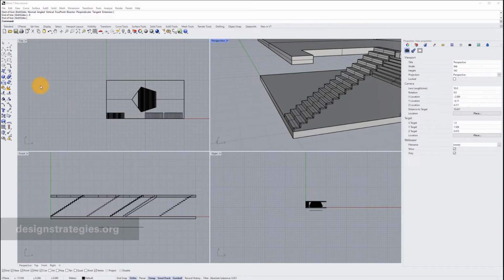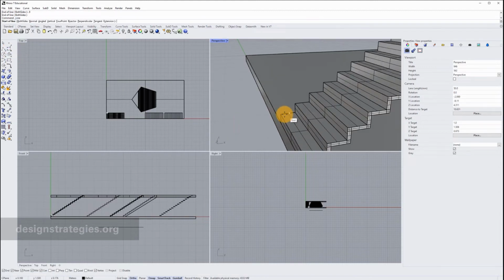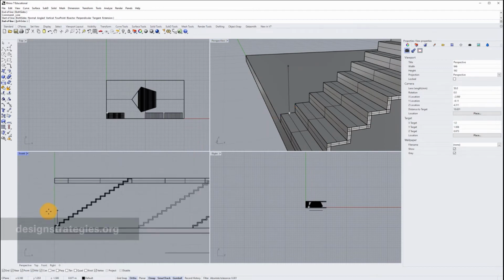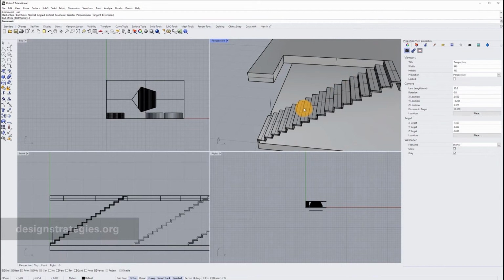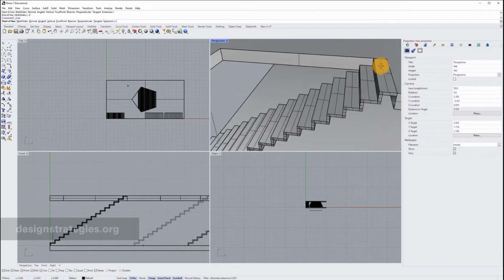The next way we want to look at how to draw a simple banister, I just take my single line and I just choose the midpoint of my staircase step here like this. And then I go into my front view and I enter a height of 90 centimeters, something like this. And I finish with my right mouse click. I do the same thing on the top. Something like this. I go here and choose my midline and just enter 90 centimeters. Okay. Then I can connect these two lines, and this already looks quite good.